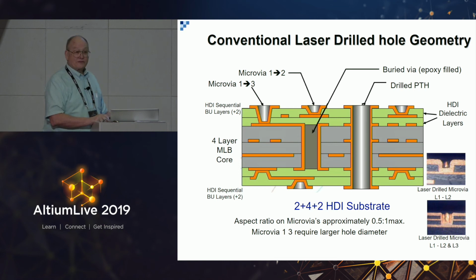And the whole day is really spent in how to get rid of these big vias because they occupy the space. And these are the ones that will fail first. The through holes always fail before the microvia. So the fewer of these you use, the higher the reliability, but also the more space you have for routing or components.